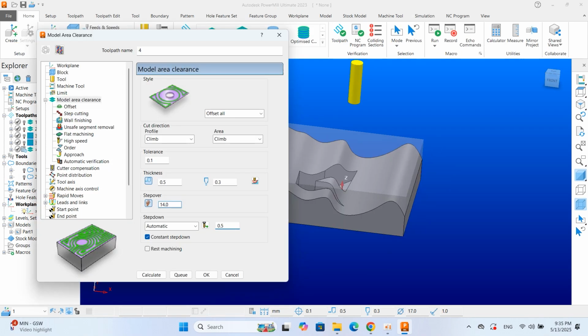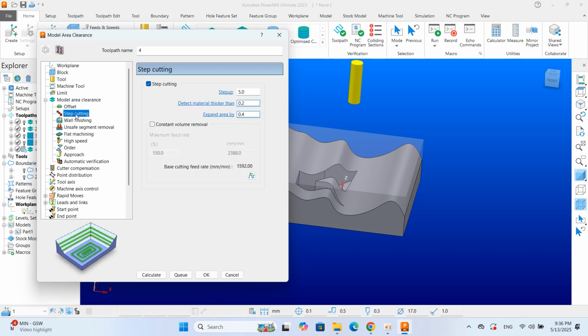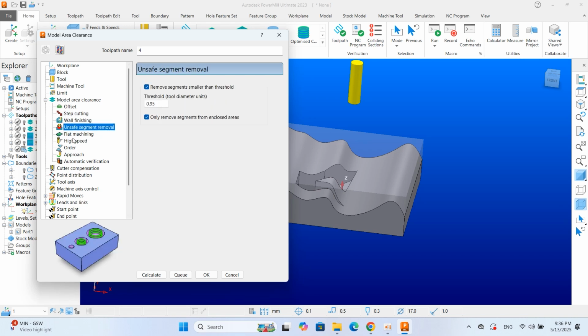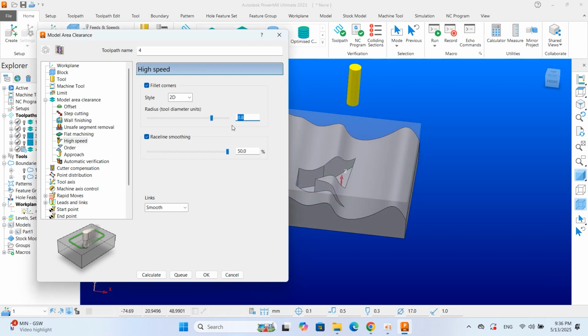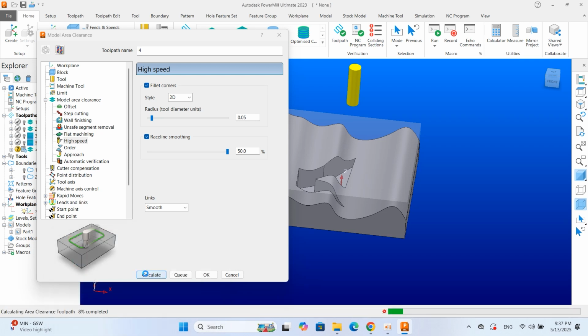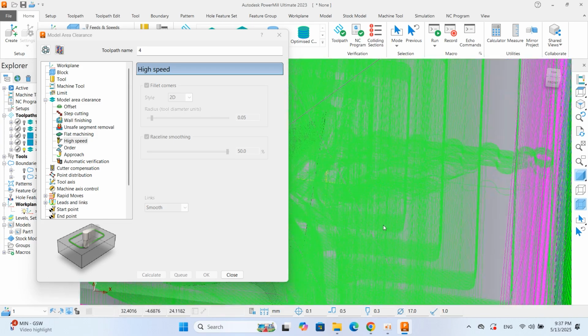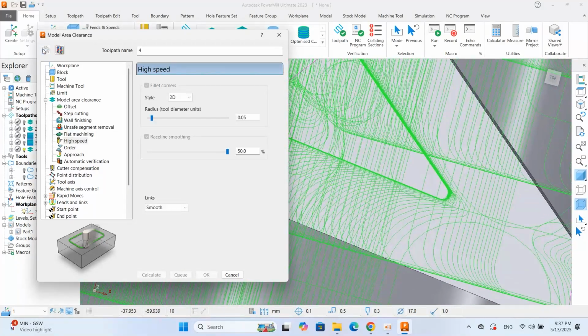Did you ever hear anything about high-feed milling? Some special tools exist for working with very high feed, 5000 millimeters each minute, but your toolpath should have special options for that case so you can use it for high feed tools. If you don't have these options or don't set them, you truly can't use it, and your special high feed tool will break.